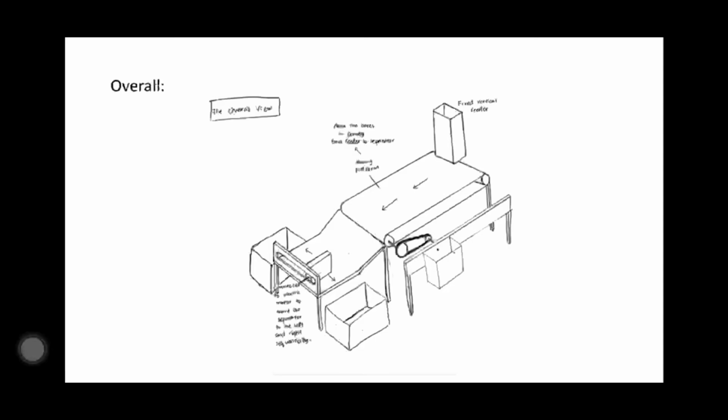For the separator, there is a frictionless surface connected to the conveyor belt so that the boxes will slide down easily. The separator is connected to the electric motor using a shaft and gears. When the motor is activated, the main gear will rotate the second gear. Then the shaft connected to the second gear will move left and right to control the separator. This is the overall view, or the real life illustration, of Redzuan's design.